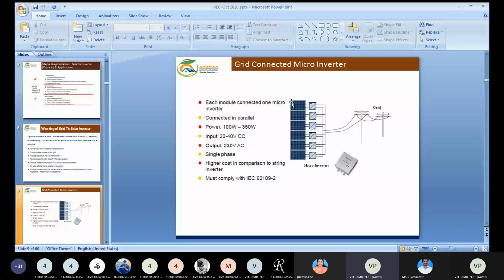The small boxes are the cells. Each cell generates 0.5 volt at maximum. If the solar PV module has a total of 60 cells, then the output will be 30 volt at maximum, and open circuit it gets 36 volt.